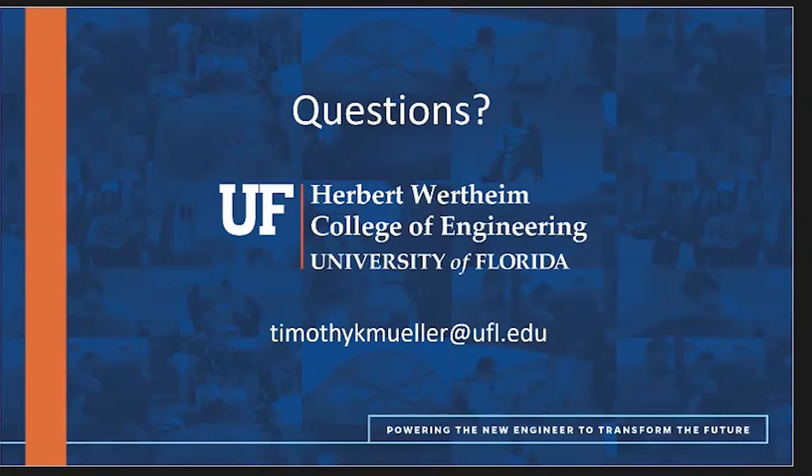Do you believe that you can use this technology for applying quality control on the manufacturer plants? Yeah, that's a possibility. That relates in the manufacturing to more of those transmission scans. Those are a more powerful scan. So if you're looking at pre-qualification, it's more viable to use more transmission because then you'll have access to put a detector on the bottom. You'll get higher quality scans out of that. So the real use of backscatter would be in the field technology.